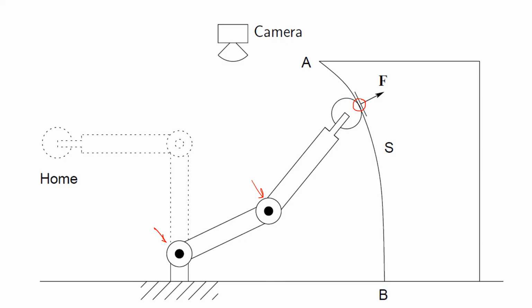For example, in our own lab, we are making one collaborative robot, and when this robot needs to interact with humans, it needs to be safe enough. It needs to adjust its own movement whenever there is a human interaction with it. And for that reason, we are implementing the impedance control paradigm in there. So there are going to be different ways in which you execute this force control problem, and that is going to be another important aspect to be considered in this whole discussion.